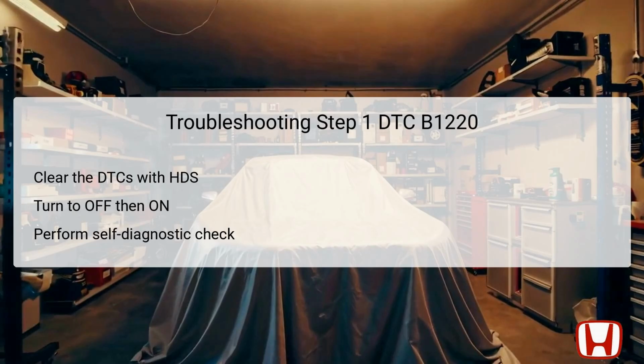Next, perform a self-diagnostic function using the HDS or the climate control unit, which will run comprehensive checks on various HVAC components and related circuits. This step is crucial because subsequent checks rely on accurate error codes. Finally, recheck for DTCs after performing these steps, as new codes may arise or confirm the ongoing issue.